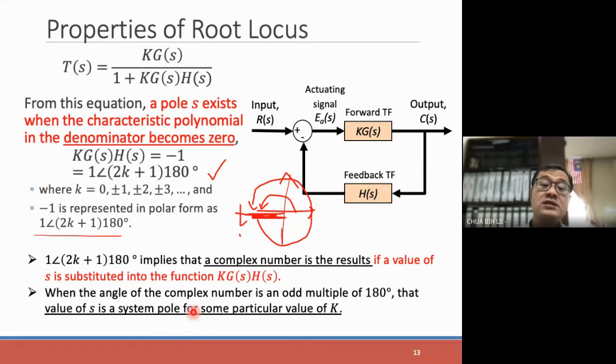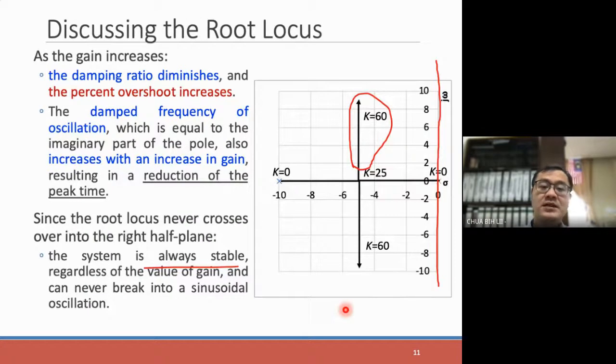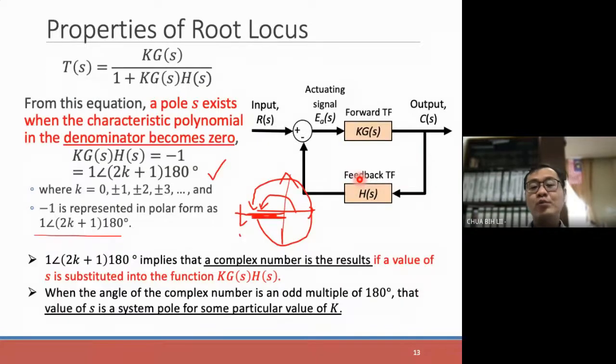Okay, so this is how we can find the k value for our system. Because in this particular diagram, when we start to plot it out, we may not want to use Excel, and then we may have a problem visualizing what the suitable values of k are. So we try to find out whether it is a proper pole or not by these conditions.